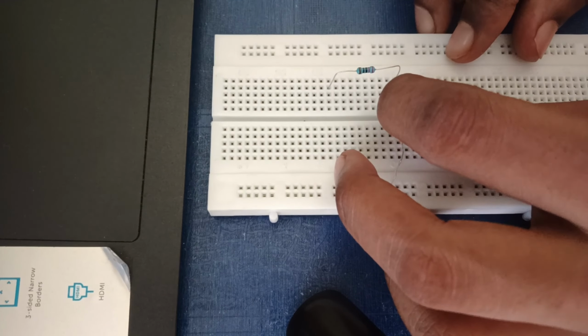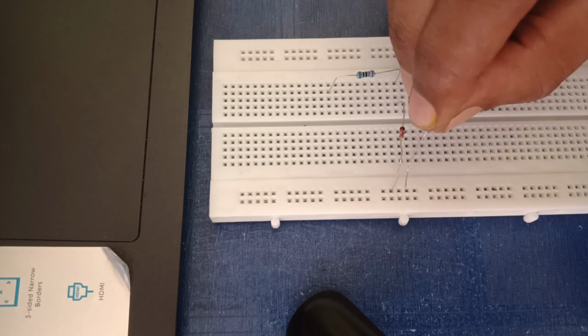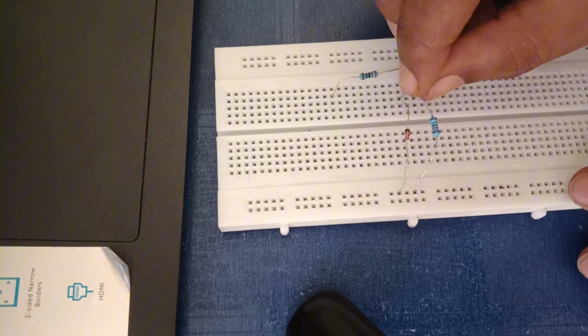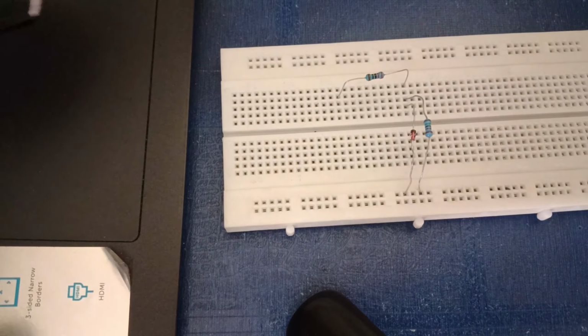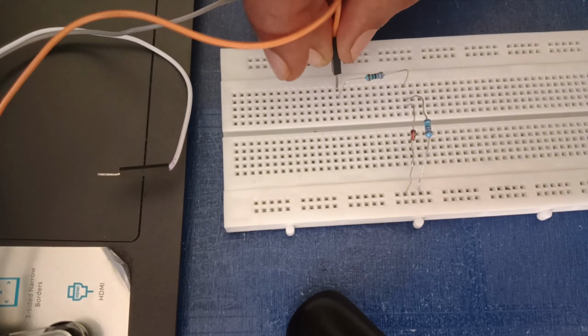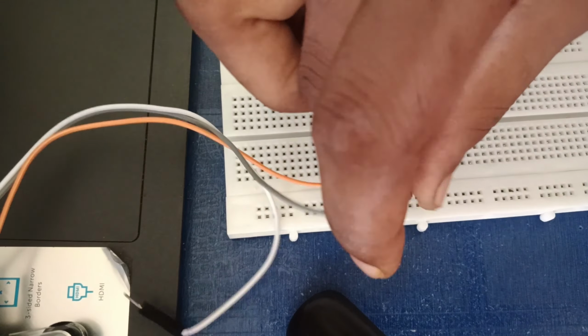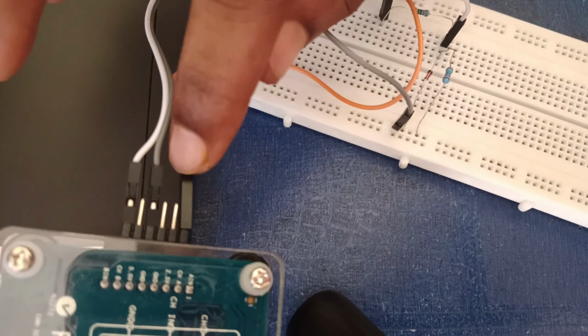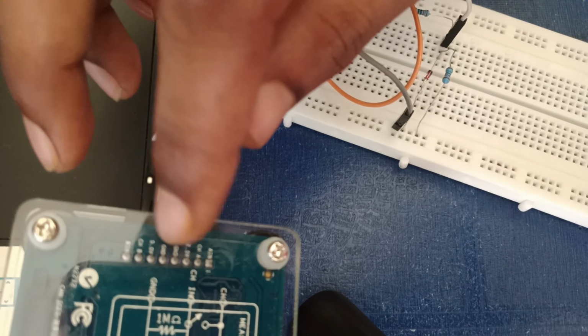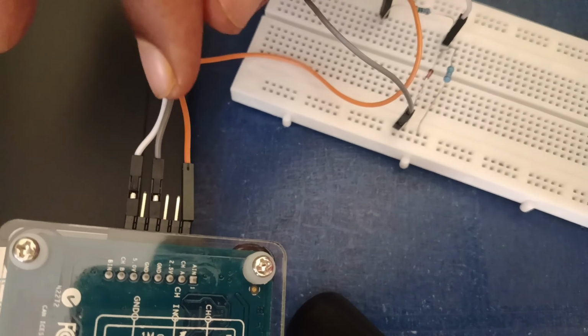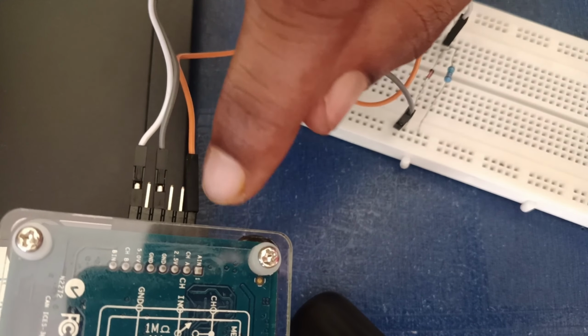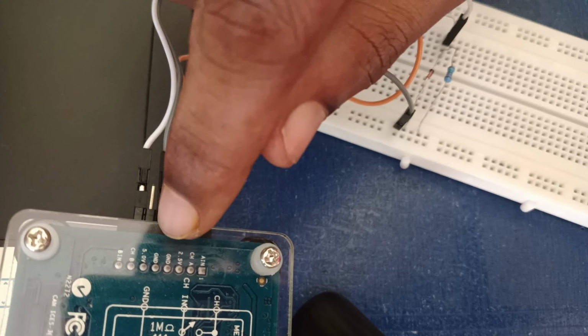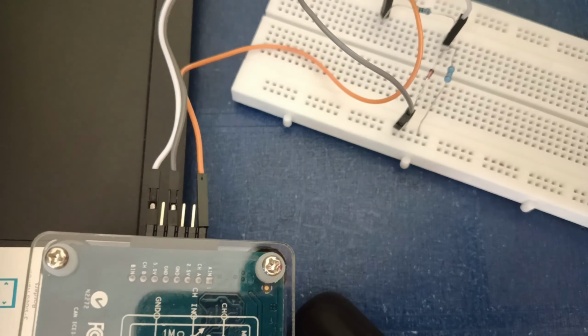So I'm going to create this circuit as provided. I'm using a 250 ohm resistor in series with the input voltage, and the Zener diode in parallel. I don't have the 20k resistor, so I will use this 15k resistor something. So this yellow wire is for channel A, this gray wire is for ground, and the white wire is for channel B.